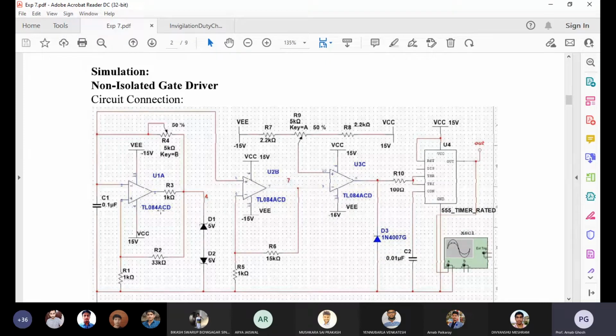So it creates the optical isolation. The first isolation is done by the transducers or sensors at the input, and the other isolation is between the DAC output and the pulses provided to your converter. That can be done by the opto isolator. After the opto isolator, we provide the 555 timer to drive the circuit. That's very basic.